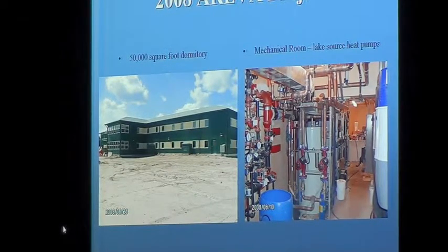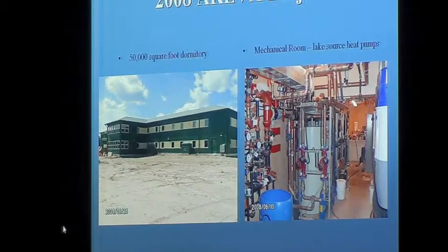But the interesting thing about it was we put this all together, and in the first full winter of operation, it was monitored very carefully, and it was 7.5 BTUs per square foot. The total energy load was 8.6 BTUs per square foot, and that included all the domestic water, makeup air, laundromats, hot water, washers, dryers, and the whole bit. And McLean Lake, I think, is at the 59th parallel, isn't it? 58th, 59th. Close to the top end of Saskatchewan.